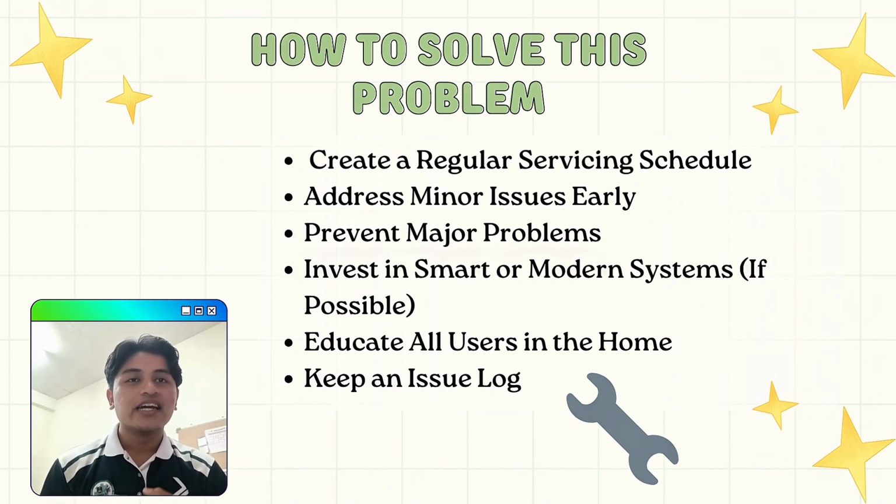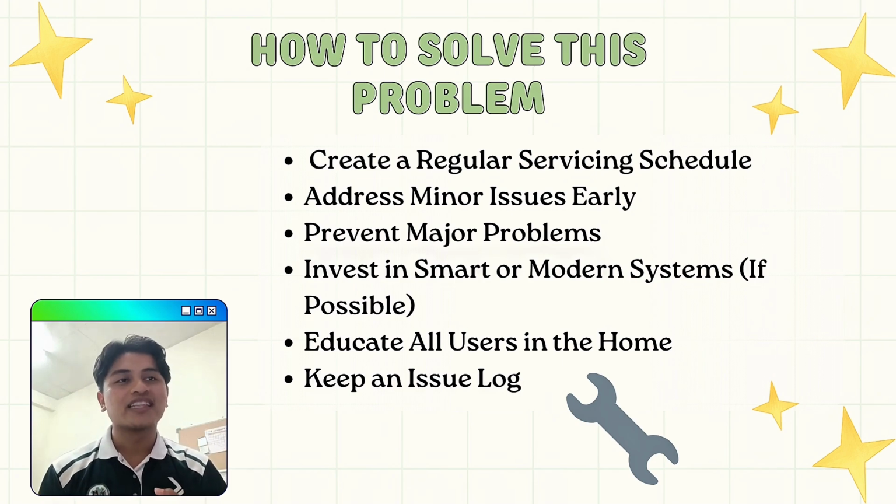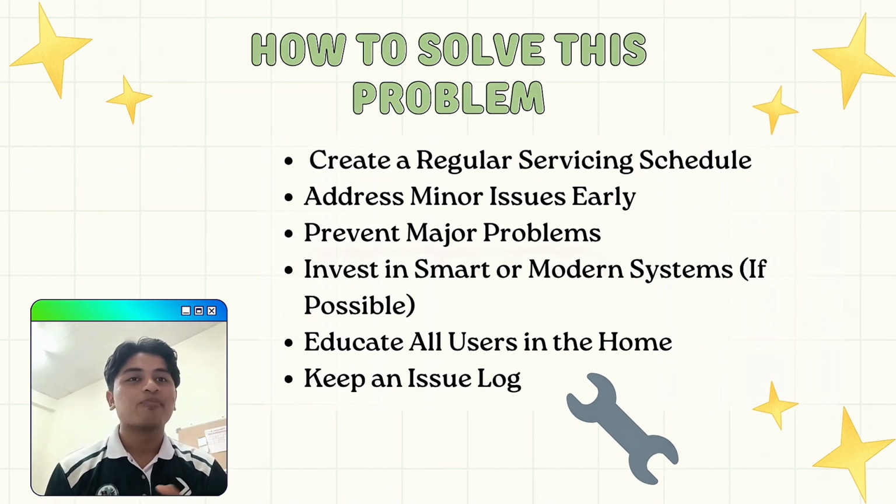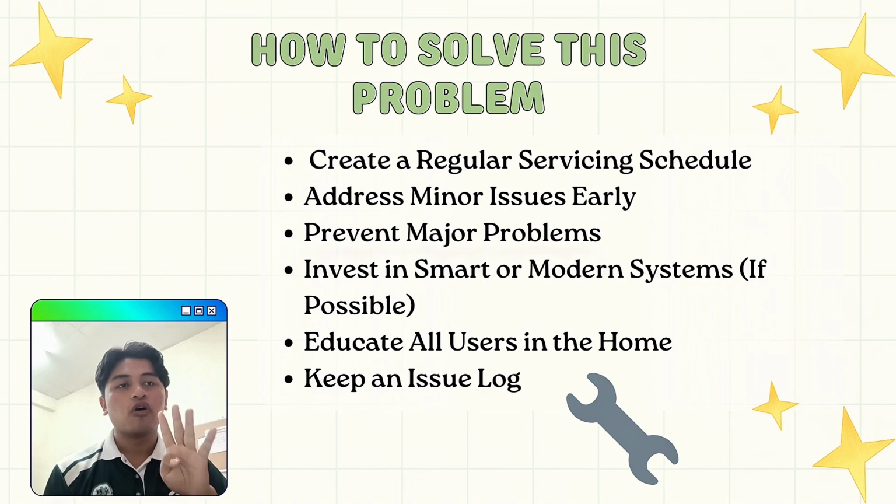In addition, early inspection, which includes monitoring gas levels and compressor conditions, can prevent big problems like gas leaks or complete breakdowns, while minor issues like limited airflow and unpleasant scents are frequently caused by filthy filters or clogged vents. Moreover, it's also critical to make sure the outdoor unit is not blocked or exposed to bright sunlight, and to clean the filters every 2 to 4 weeks.